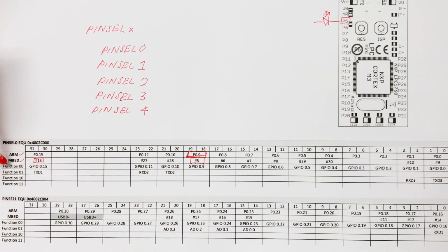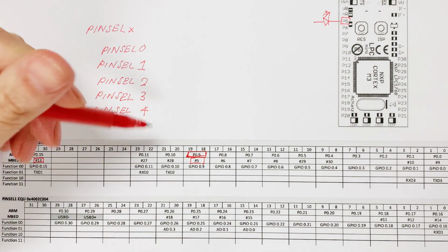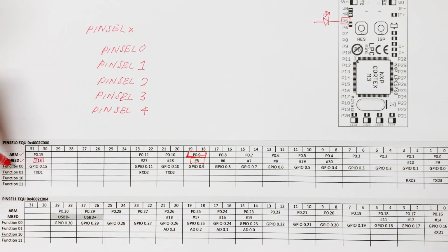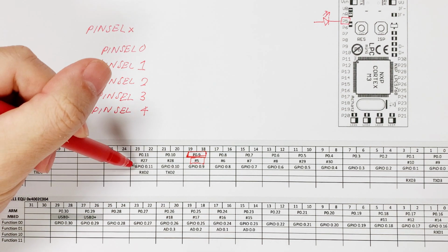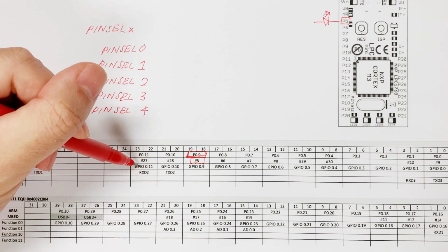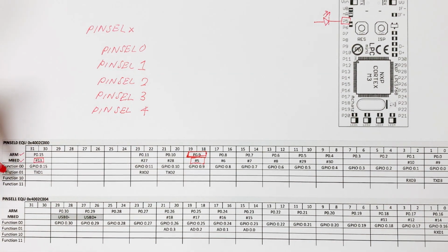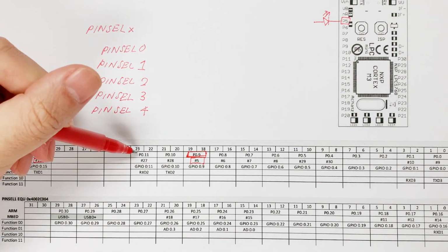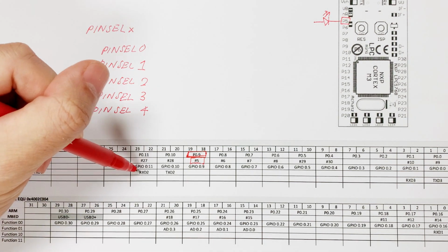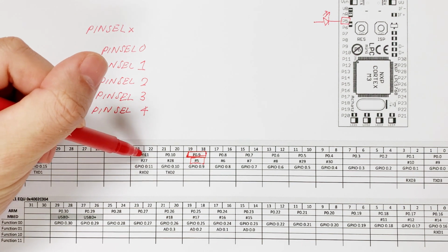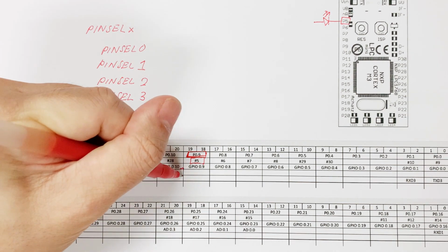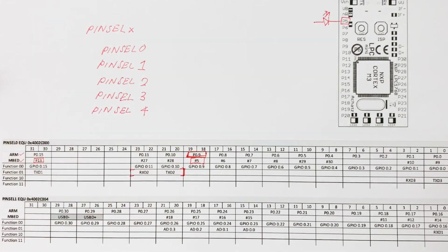For example, there are 4 different functions that you could assign to a pin of the microcontroller. For function 00, the pin will behave as GPIO, which basically means digital input or digital output. If you look carefully at the table, some of the pins have a second function, function 01. Port 0.11 and port 0.10 are the TX and RX for the UART interface.